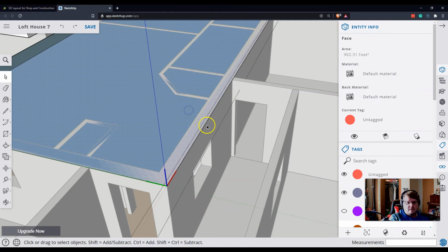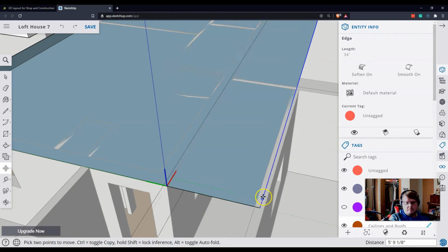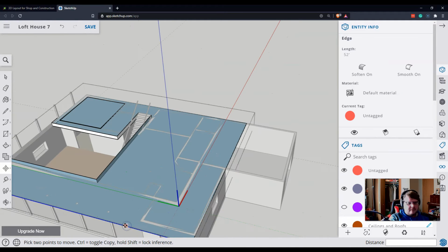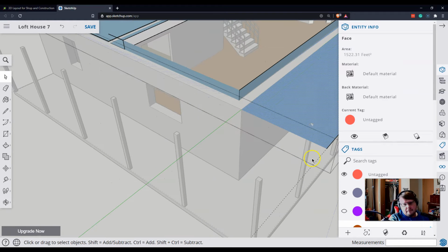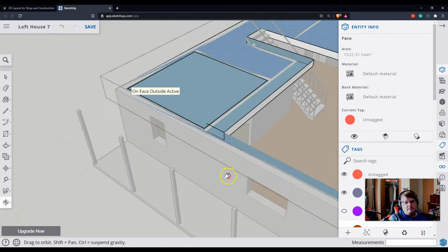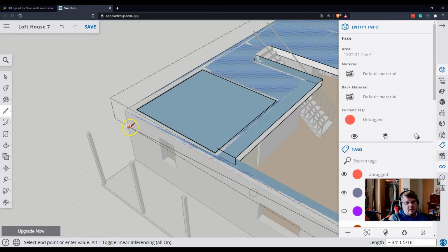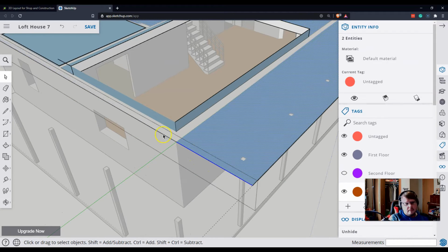So here's what we'll do. We'll take this, and what I did when I was working through this is I just moved these lines on the, so keep it up, make sure it's on the green axis, move that ceiling out to where it needs to be. So we'll select this one here, and then move it out to that 2 feet past the eaves, and so you'll see how that works. Oh, I did erase this bit here. So I'm going to draw in that line to there, and then draw in that line to there again. And then move this out.